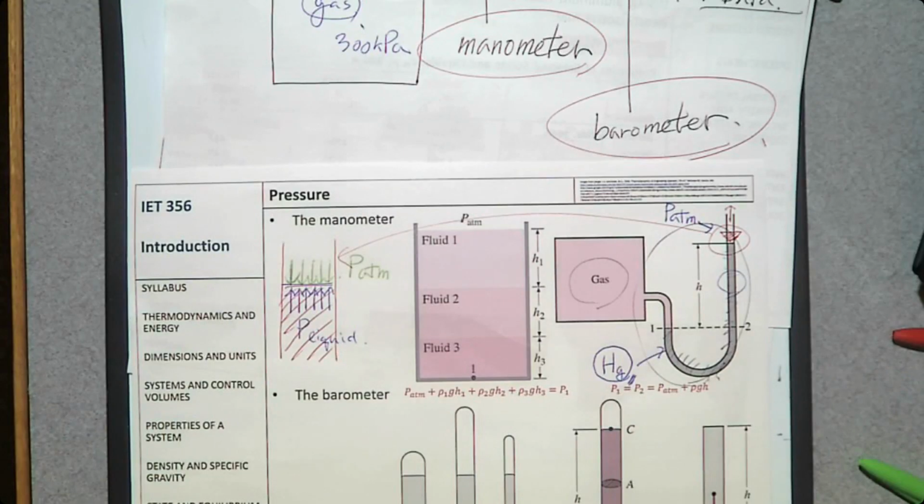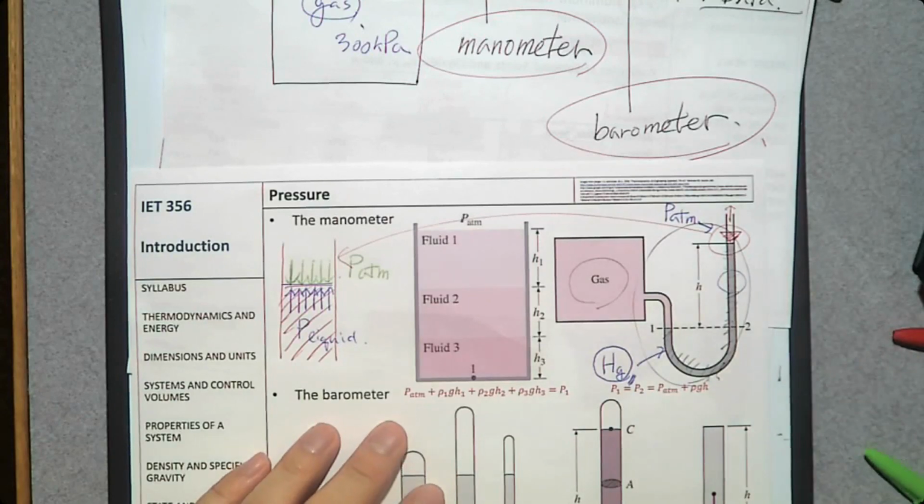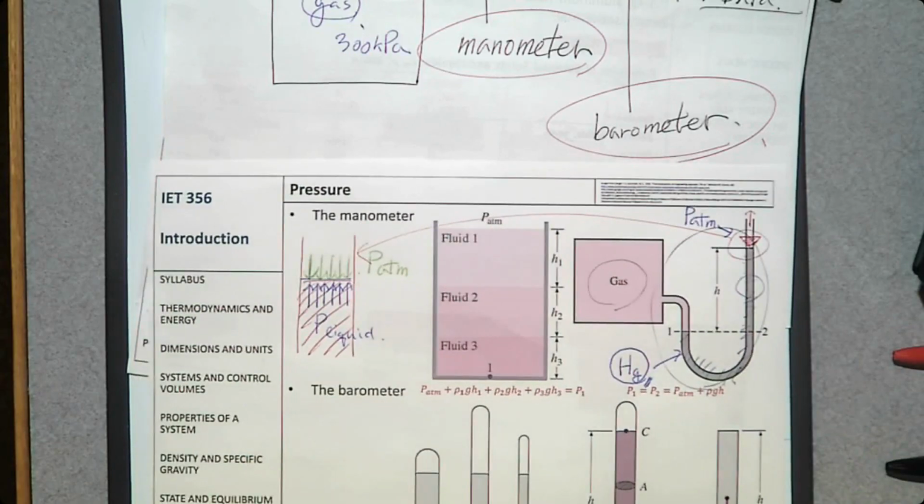So at this interface, there's a gas pressure acting here and a mercury pressure acting here. Okay? You need to have a ruler or something, and this should be an input. So assuming that we know the H value, then you can calculate the pressure inside. Then, what is the equation that we know? Delta P is rho g h.